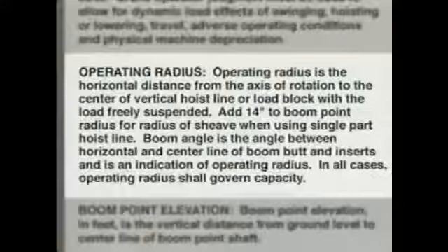The rigger on the ground selects the equipment for the job based on the weight of the load and how the load will be rigged. As he selects the equipment, he inspects each piece for wear or damage. At the same time, the crane operator checks the capacity charts to make sure that the crane is of adequate capacity to handle the load. Then the rigger directs the crane operator to position the load hook and slings directly above the center of the load. He then attaches the rigging equipment to the load.